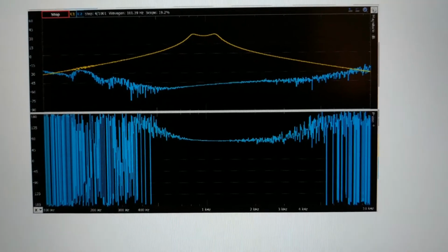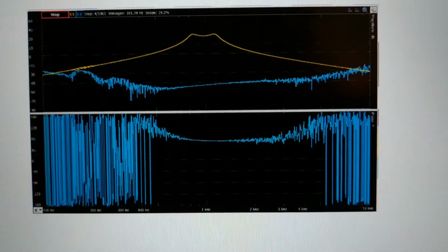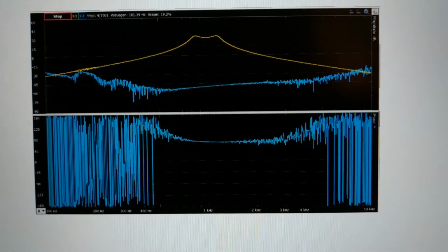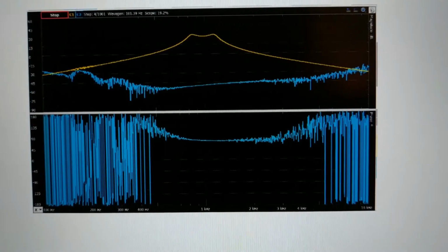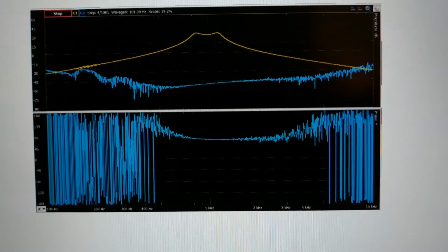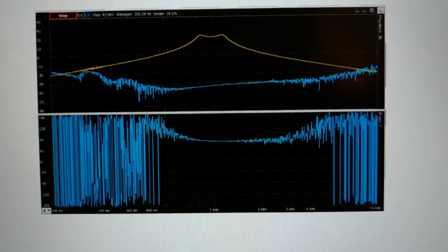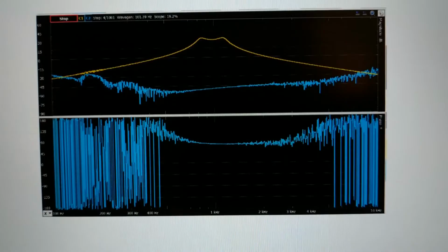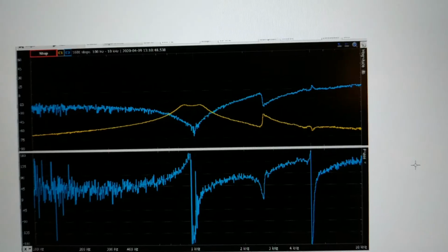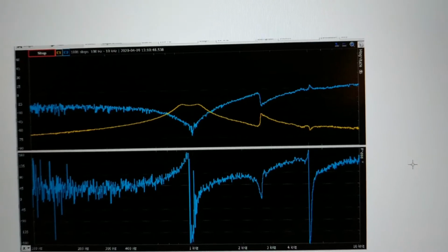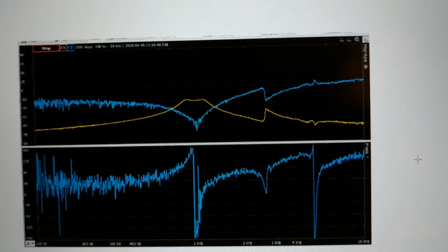We performed an AC frequency sweep on the filter in order to test for functionality using the waveform software. It should be noted that this first test was performed by directly wiring AC signals into the filter. In other words, we had no interaction with the microphone in this test. We performed a second, similar test on the filter in which the microphone was taken into account.